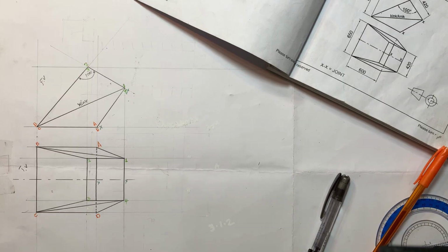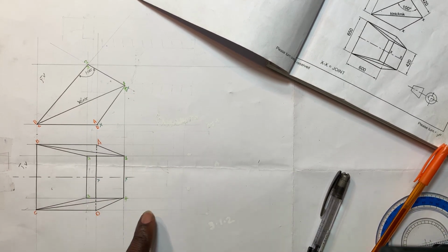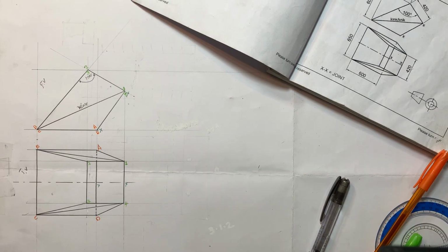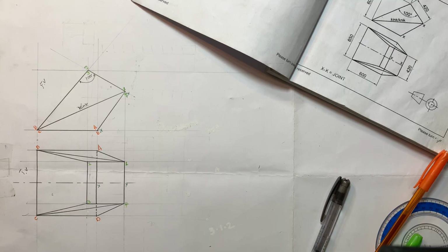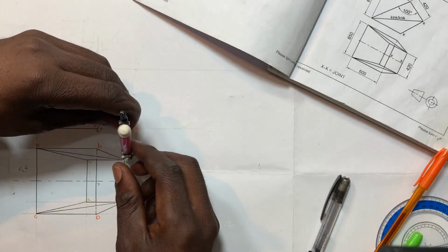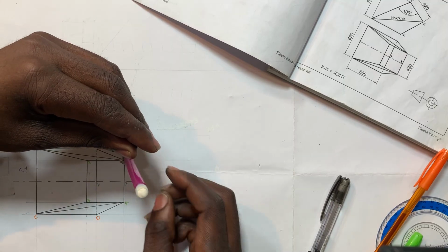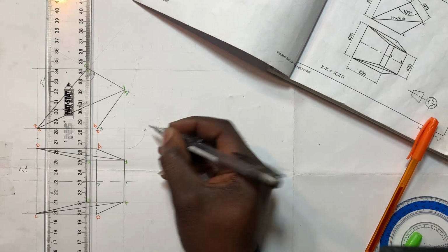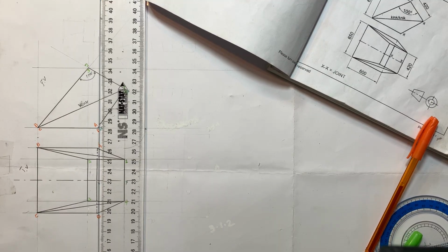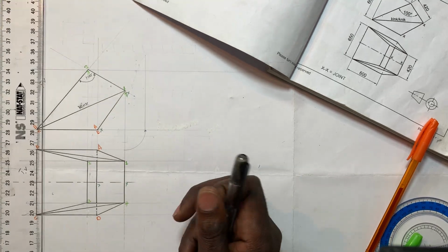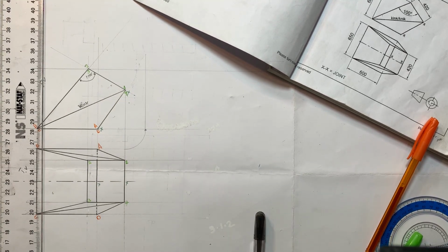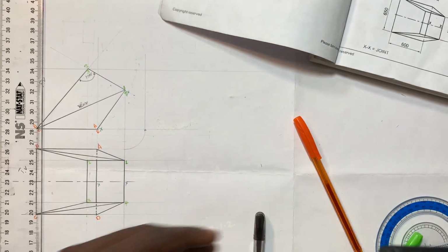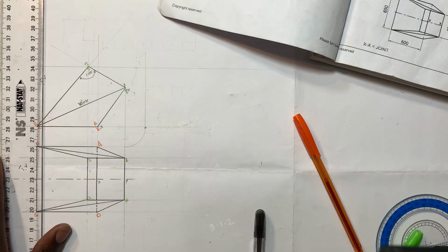So what I normally used to say, I'll start my development right opposite to the cutting plane. You understand? So how? Simply place my drawing compass at this point, further extend it to here. I'm looking for the true length diagram now. Then once I touch this bottom part of our front, I can just have a vertical constructional line. Vertical constructional line. Understand?